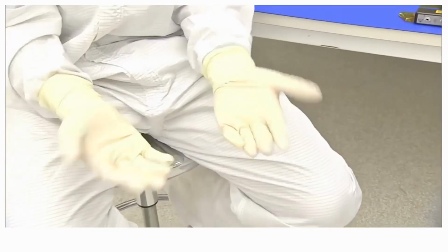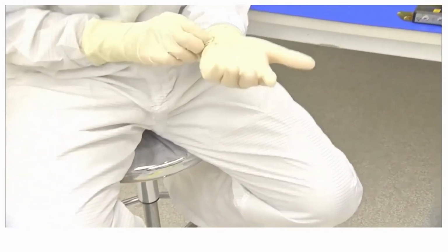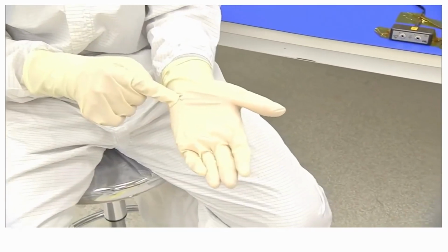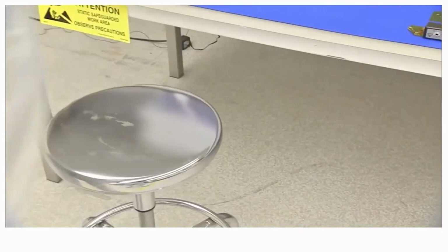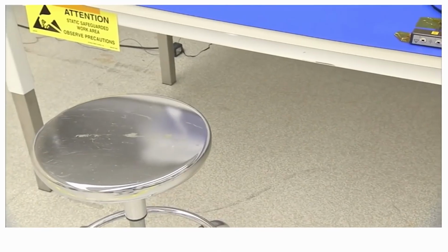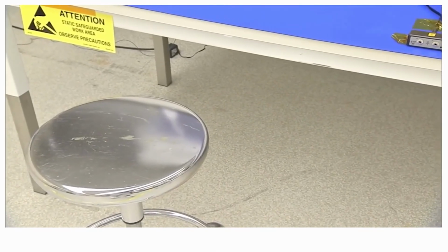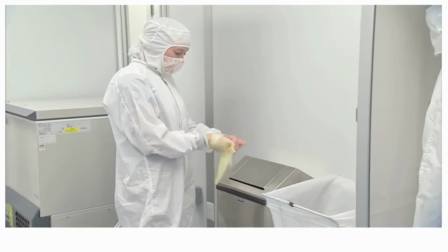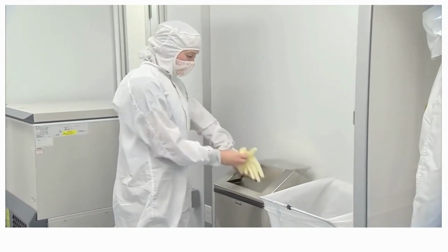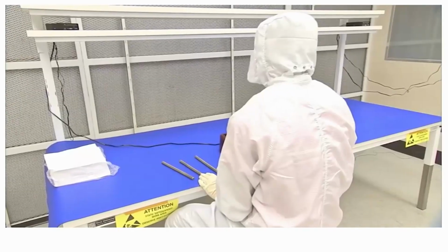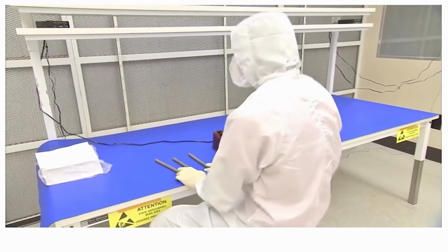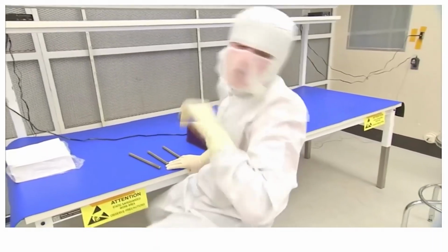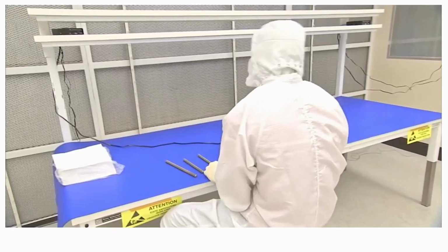Be sure to check your gloves regularly for any rips, tears, or contamination. If your gloves are damaged or contaminated, exit the clean room and change out of your gloves in the gowning room. Your skin can introduce large quantities of contamination, so properly covering your hands is essential for protecting the hardware. If you have to sneeze or cough, be sure to do it facing away from the equipment. Do not cough or sneeze onto your gloves.